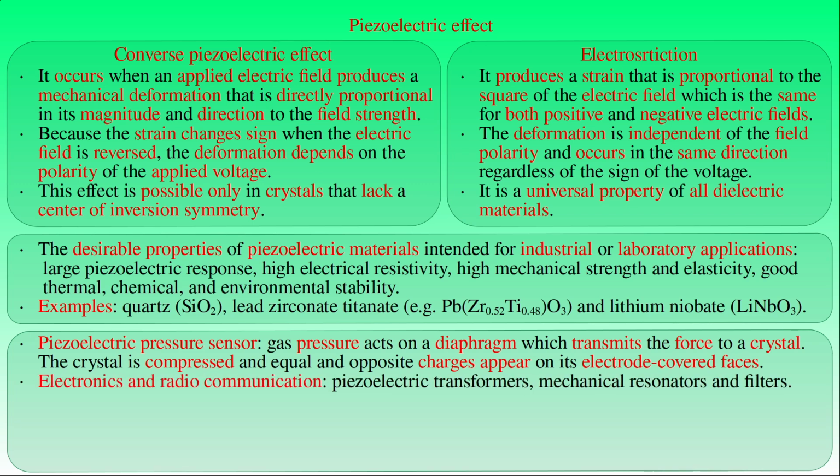Another area of applications of piezoelectric materials is modern electronics and radio communication. For example, piezoelectric transformers used in LCD monitor backlights or in AC adapters convert electrical energy at one voltage into electrical energy at another voltage using mechanical vibrations through the converse piezoelectric effect. Piezoelectric crystals or ceramics are also built into electronic oscillators, frequency filters, and ultrasonic transducers, where they act as a mechanical resonator with an extremely well-defined resonant frequency. Quartz filters provide extremely stable frequency selection because quartz has a very high mechanical quality factor, and crystal oscillators apply piezoelectric crystals to stabilize the frequency of an oscillator.